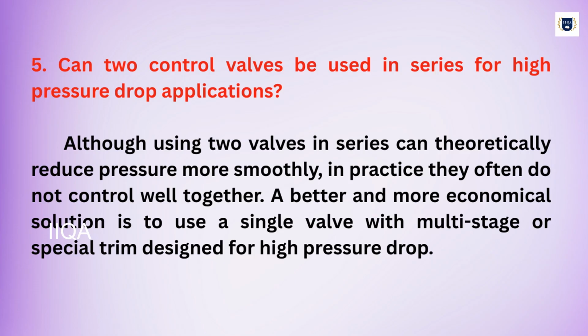Can two control valves be used in series for high-pressure drop applications? Although using two valves in series can theoretically reduce pressure more smoothly, in practice they often do not control well together. A better and more economical solution is to use a single valve with multistage or special trim designed for high-pressure drop.